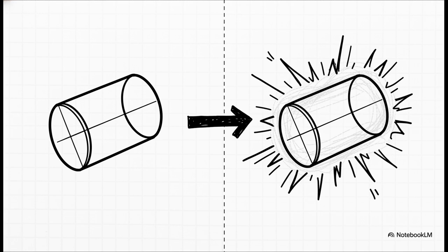Circular runout exists primarily because rotating parts absolutely must function smoothly in service. By controlling that functional rotation, we directly reduce dynamic vibration, which, you guessed it, solves our brake rotor issue. But it goes way beyond just brakes. It ensures proper bearing performance by preventing uneven loading on ball bearings, which would otherwise literally tear an assembly apart at high RPMs. It's also absolutely crucial for evaluating dynamic balance constraints.